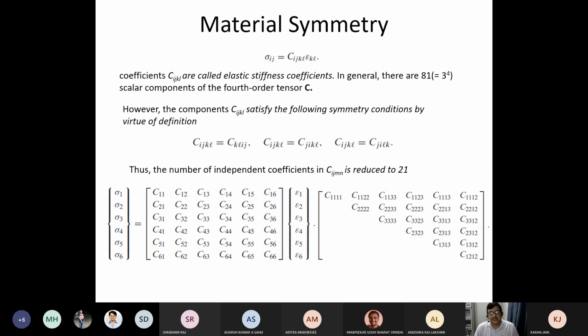So the material is symmetric around that. But if they are not, then the material is anisotropic, and you have to consider 2 different moduli in 2 different directions. Right? So one puts various symmetry arguments on this Cij. So first is this symmetry argument.